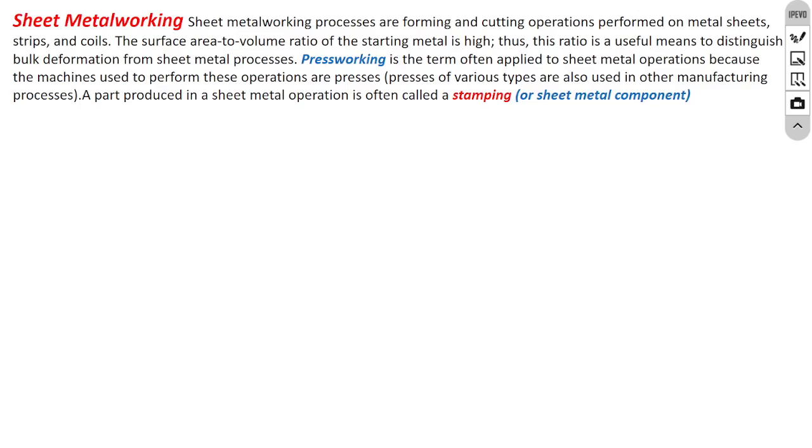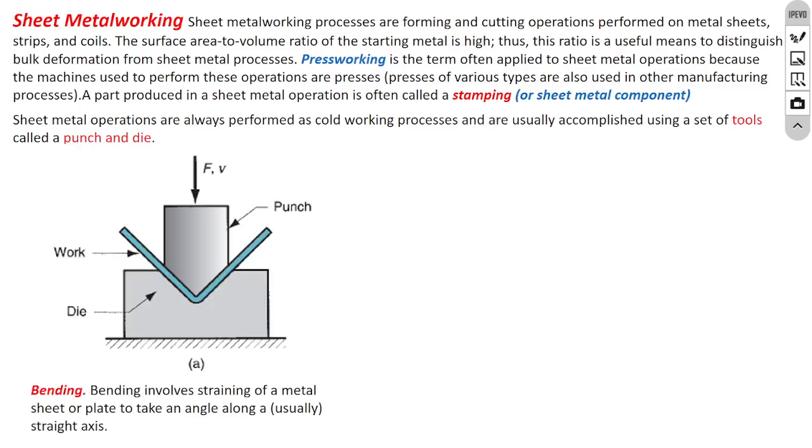And sheet metal working, the thickness is considerably smaller than the width and the depth of the prism. It is called sheet metal, and the shaping process is called sheet metal work. It is a press work actually. As illustrated in bending, we have a die, and applying the deformation force, we can bend the sheet and change its geometry.